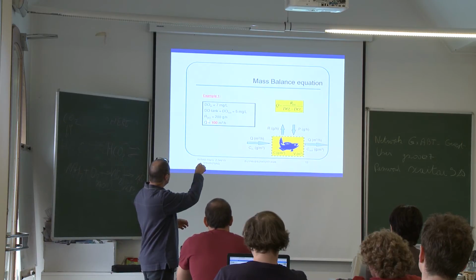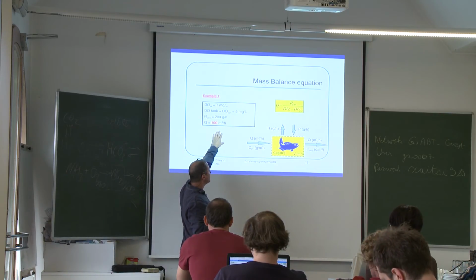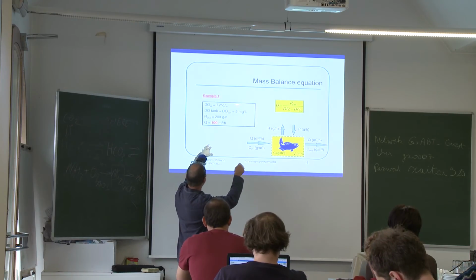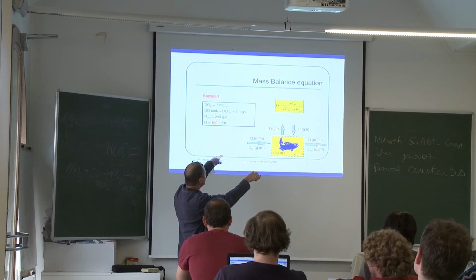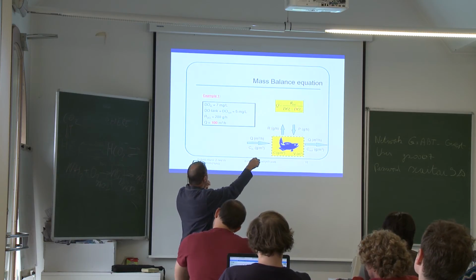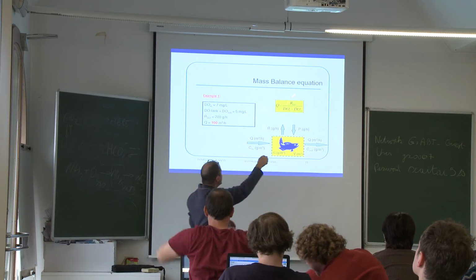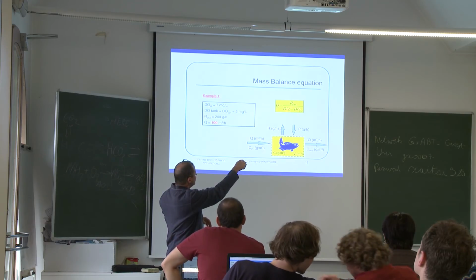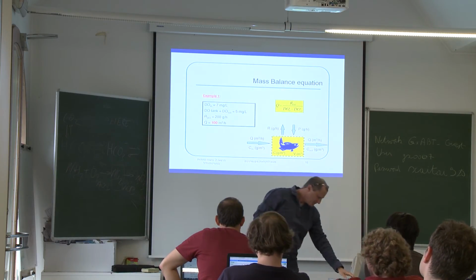So we know that the Q, the flux in, has to be 100 cubic meter per hour in order to meet our constraints of the outlet concentration, because the Q, which is our unknown, equals the removal rate over the difference in dissolved oxygen concentration.